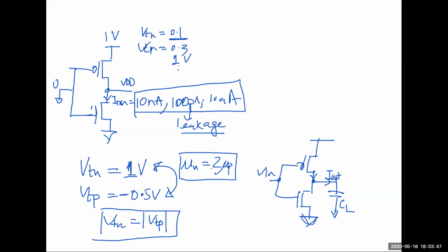So the capacitance is going to charge, and initially when it is charging, it is going to pass current, and then when it is fully charged, the current is going to stop. They asked this very clearly: if input goes from 0 volt to 1 volt, zero logic to one logic, and one logic to zero logic, then what's going to be the diagram of your output current, the current through the capacitor?